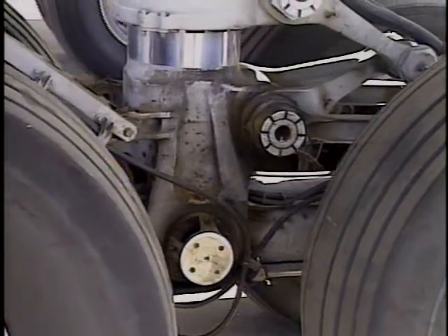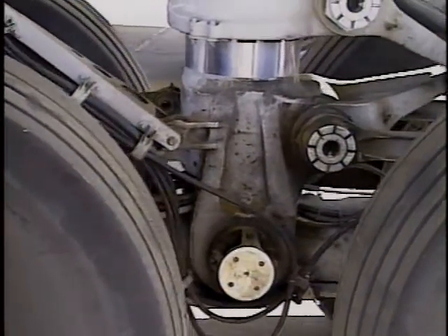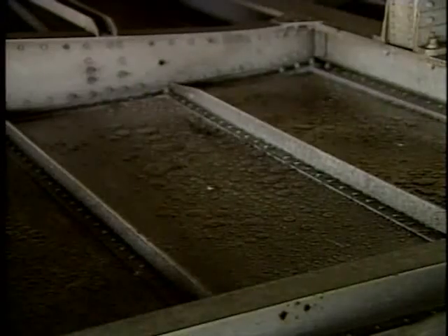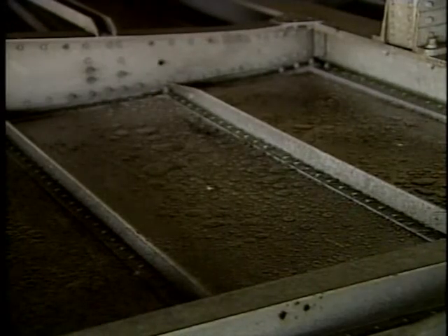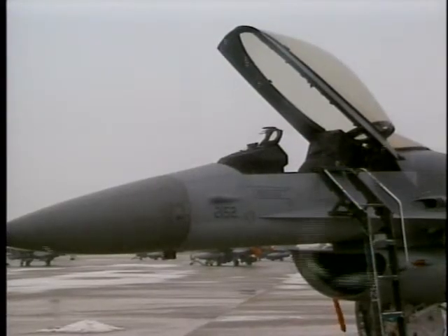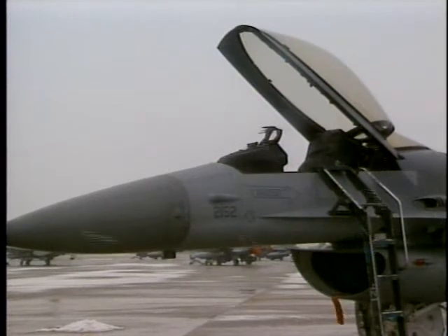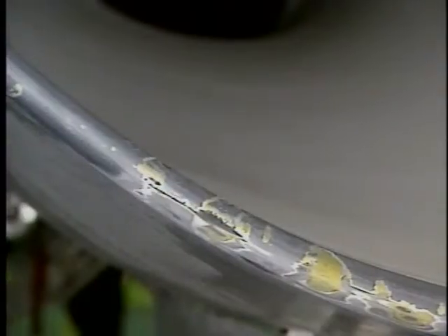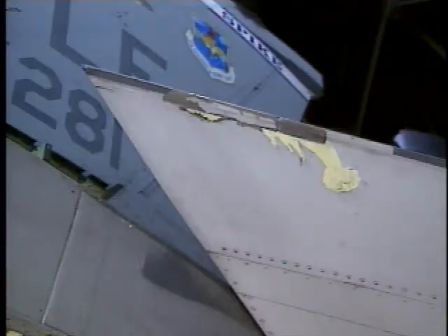Wheel wells and landing gear assemblies are extremely susceptible to corrosion because of the elements they are exposed to. These areas are also vulnerable to water entrapment. Open flight stations and aircraft cargo bays are vulnerable to these elements when open to aircrew entry and cargo loading. Engine inlet and aircraft frontal areas, such as leading-edge surfaces, are constantly undermined by rain, dirt, dust, and other abrasive elements.